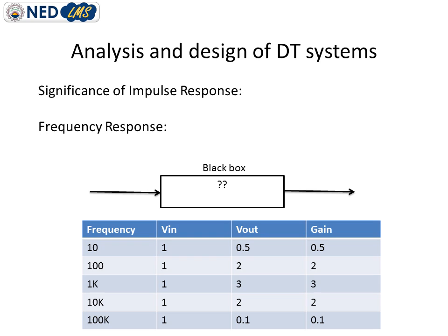Ideally output would also be obtained only for n is equal to 0. But if we obtain output for other values of n, such as n is equal to 1, 2, 3 and so on, that output is specifically due to the nature of the system. That's why the impulse response is often known as the natural response of the system.